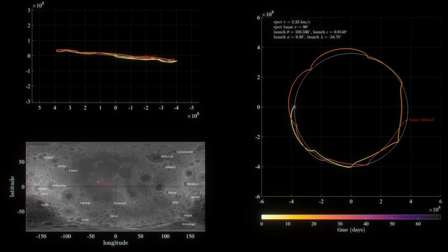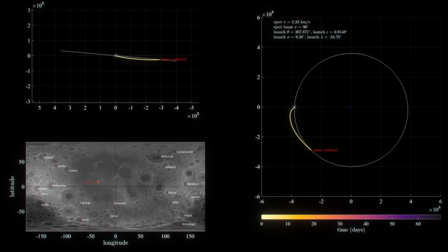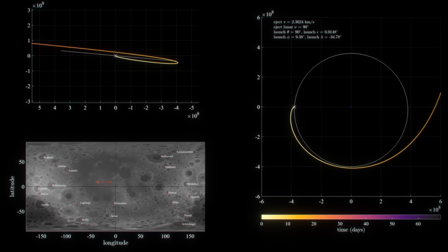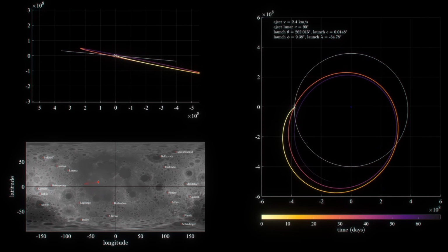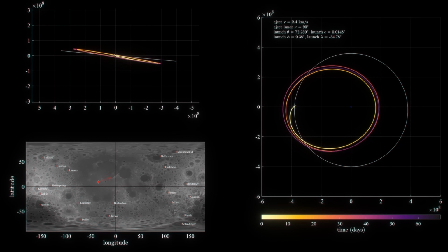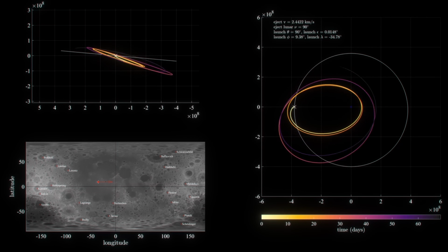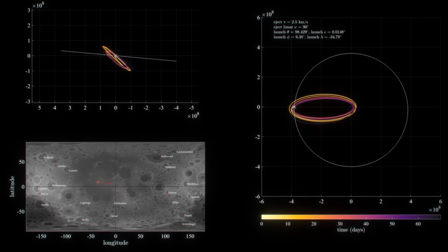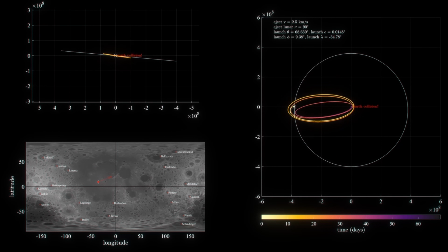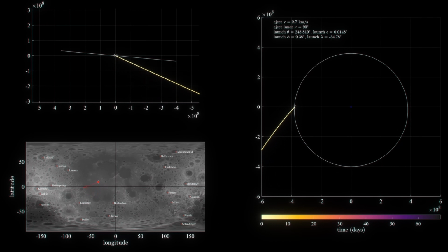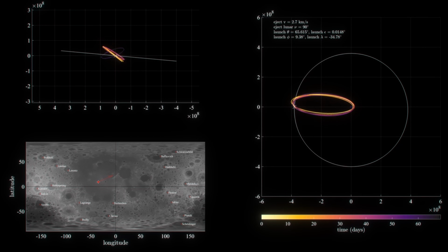Then, if we combine azimuth with ejection velocity, which is basically controlled by finely adjusting the electrical parameters of the mass driver, we get a much richer design space. We are no longer just choosing where to point the gun, we are choosing from a whole family of lunar exit trajectories. In our convention, an azimuth near 90 degrees gives us a more retrograde departure that is useful because it helps with in-plane maneuvering, especially lowering periapsis deeper into Earth's gravity well, but it still leaves the rocket pod with a lot of inclination change work to do later.